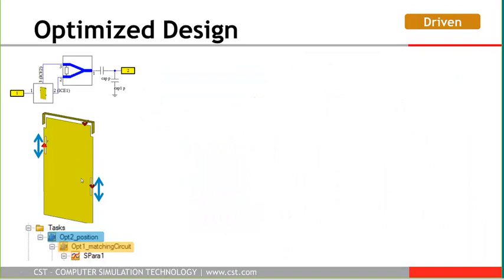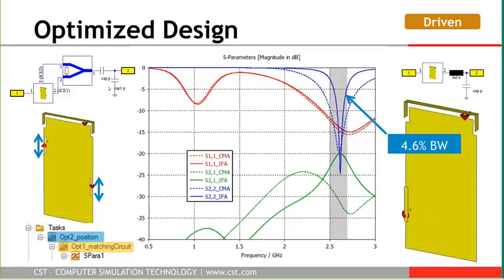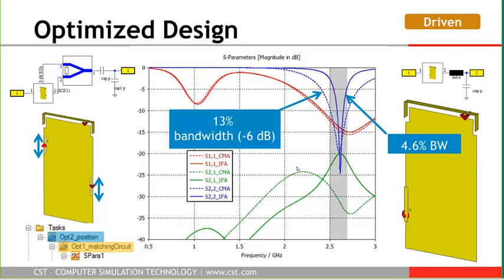So let's try it. Let's put it to the model. We will need some feeding network here at the top, represented by ideal Wilkinson divider, and again matching network. We use the same logical process as in the cases before. Again, the standard design is displayed as a blue curve, and the CMA design is displayed as a dashed curve.